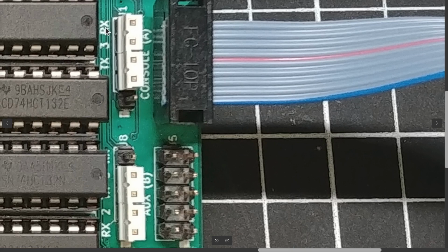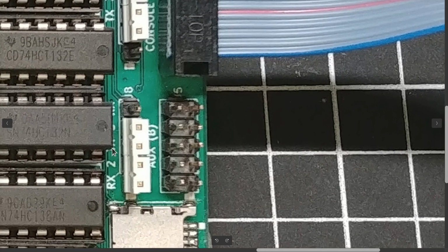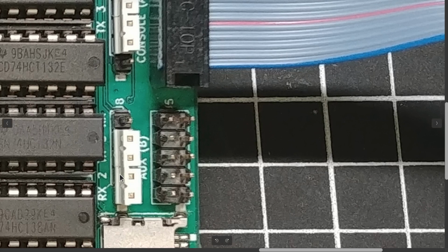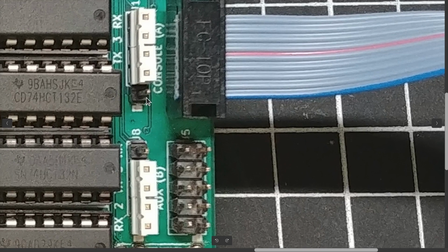As shown here, you can see RX, TX underneath this chip. Down here, it says 2 for this pin here. They're both labeled the same. So underneath this chip that's blocking your view here, you can see that there's a 2 labeled for this pin here, and this pin here is labeled as one down here is for receive. Okay, so the idea is that pin 2 here represents which pin on the DB9 is going to be connected to either the receive signal as shown here when the jumper's down like that, or it's connected to the transmit signal when it's up like this one is here.